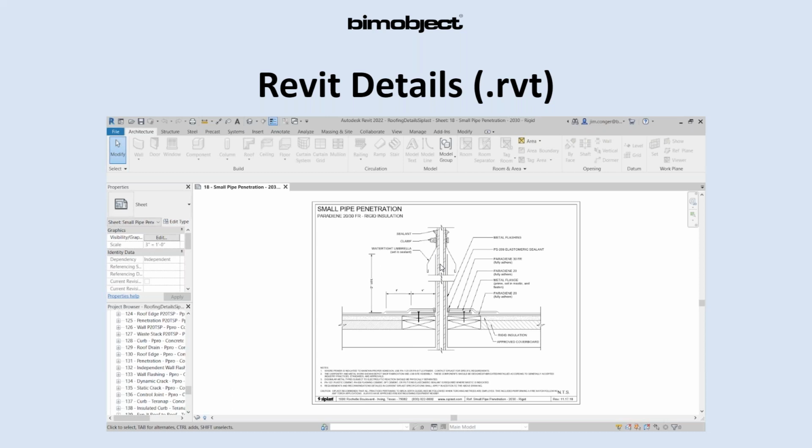So when you have a penetration coming through, this is how many layers you're going to have at this point. Here's where your cant strips are going to be. Here's where you're going to put your turn bars and clamps and sealants and yada yada. So it dictates to the installer exactly how they're going to do it.